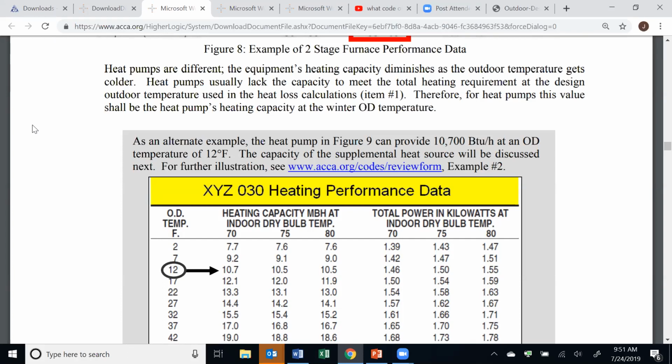Is there... so I know the energy code requires a lockout on the heat strip when the heating load can be handled by the heat pump. So you're saying if the heat pump's running and the strip heat's running at the same time, what does that do to the equipment? And why don't the manufacturers keep that from happening?